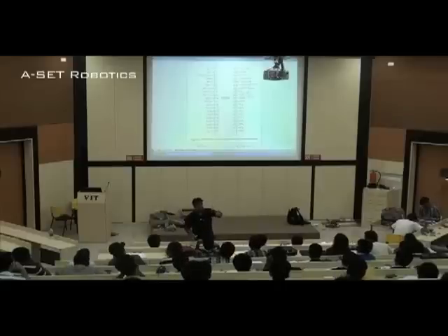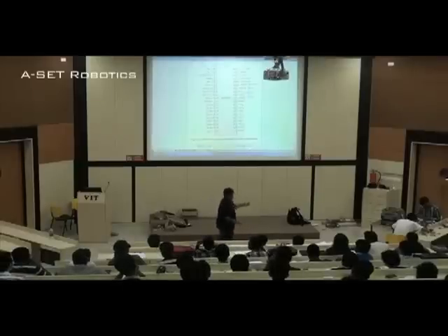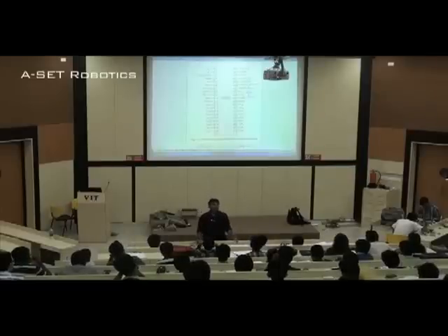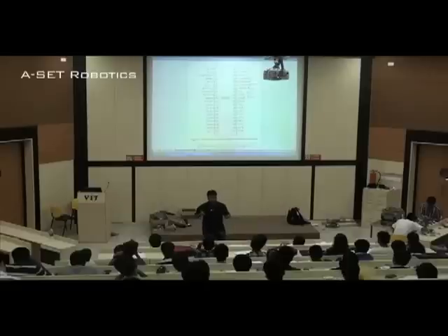until and unless the memory gives a ready signal to the microprocessor, the microprocessor will go into wait state. Because the memory would say, hey, I am a slower device, you have to give me some time, I'm searching it, I'm taking it out.